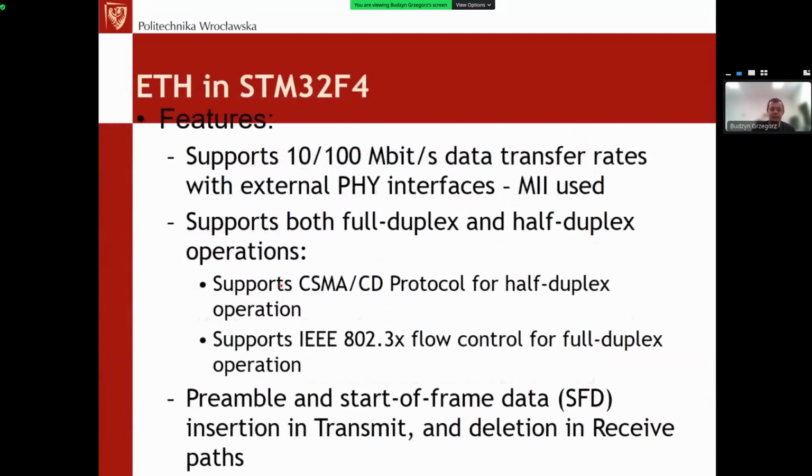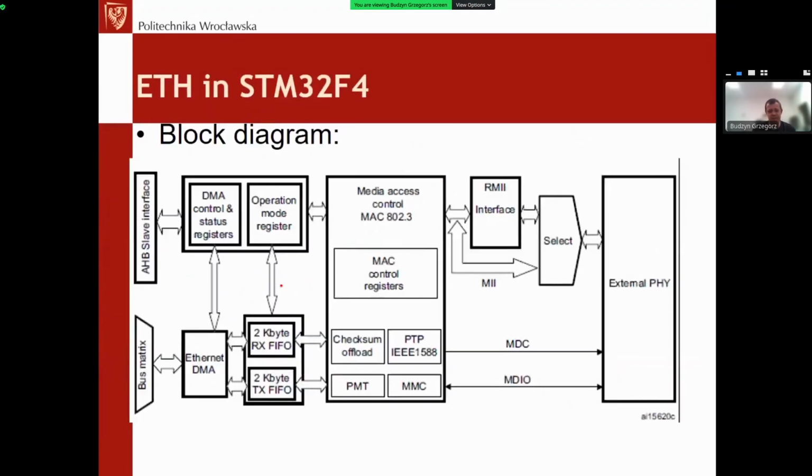So concluding, Ethernet itself is possible. It is available, like you can see here in the Ethernet block in the STM32F4. Still, there are 2 major problems with the implementation. Problem number 1, software: if we want to connect to the internet, usually you need to implement a TCP/IP stack. So either use a ready stack or do it by yourself in a limited version.